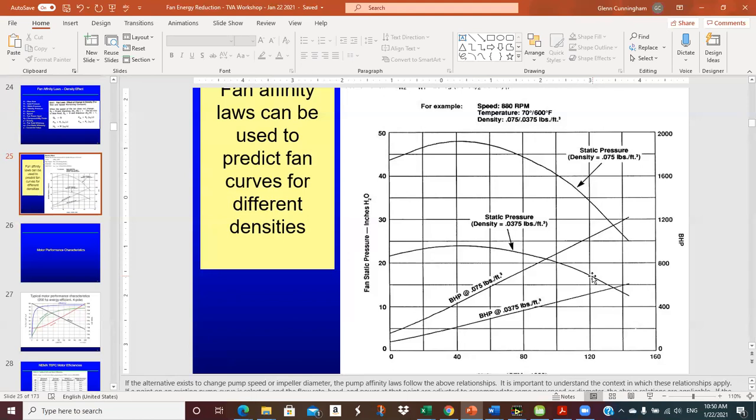But I've used a Pitot tube some, and it's a challenge. It really is. You've got to get a good location, and you've got to do your best to get it pointing directly straight into the flow, and try to get your positions correct. So taking good Pitot tube measurements is not easy. It takes some work and planning.